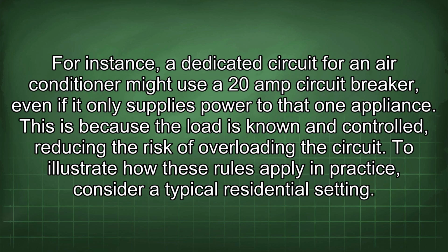For instance, a dedicated circuit for an air conditioner might use a 20 amp circuit breaker even if it only supplies power to that one appliance. This is because the load is known and controlled, reducing the risk of overloading the circuit.